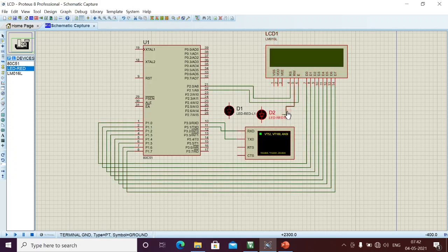I'm just adjusting all the data so that we can connect simply. This line I should connect to the ground. Similarly, this line also I should connect to the ground. Here it is a common cathode configuration, so all the cathodes should be connected to the ground. Here 2.2 I should connect to the bulb. This is the light. Next, 2.3 I'm going to connect to the fan.